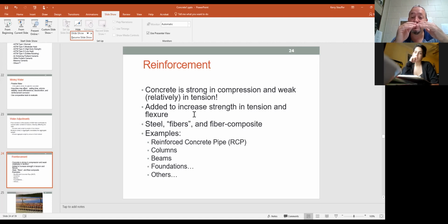So in that scenario, if that's the only load condition that we had and we just had positive bending, we would want to put the rebar or the reinforcement in the bottom of that beam. Now, there are other things that have been developed in the last several years. They've really not caught on, and rebar is still your predominant reinforcement.